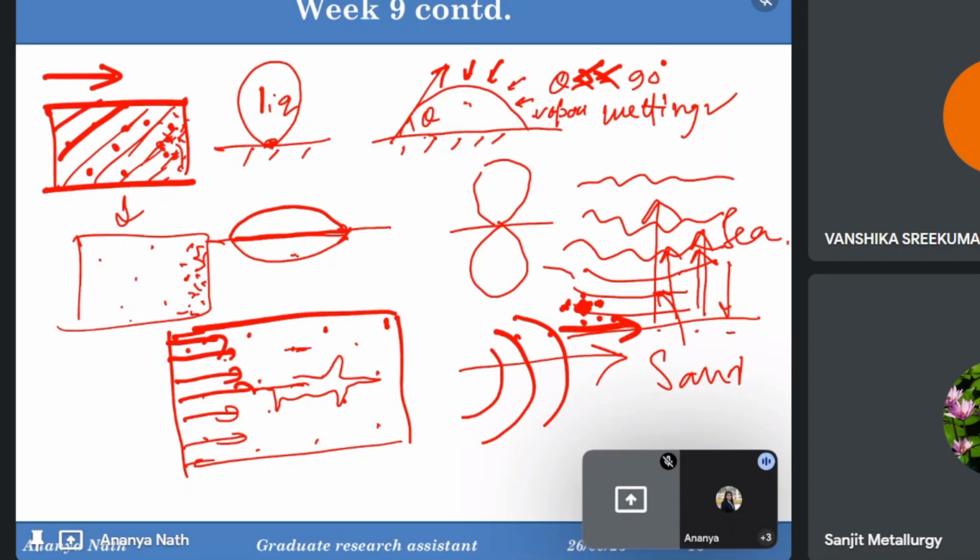So how are we cooling it? We may cool it unidirectionally, or from all directions, or with a high cooling rate, or a low cooling rate. Depending upon that, the solidification front will be present, and also on how much is the thermal conductivity of the reinforcement particle and the metal. Depending upon the ratio of that, this agglomeration or engulfing of particles will be decided.